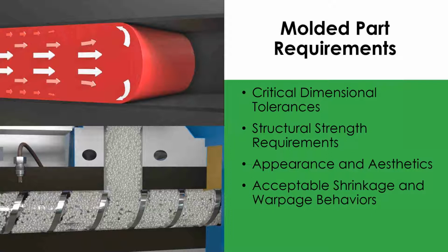Now, what's the warpage behavior of a part? To be honest, if a process engineer at the machine sees part warpage, in general, he has very little opportunity to solve this problem. Shrinkage and warpage behavioral problems should be designed and optimized out of a part and not in the molding stage. So part design optimization is very key before you actually build a mold and before you even process a tool.